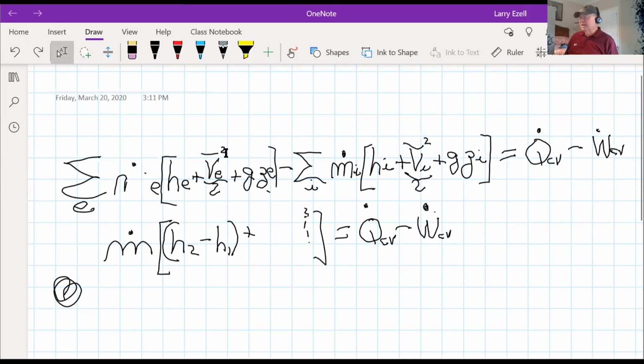But the important thing in the second law I was going to mention: this energy equation, or the first law equation, doesn't say anything about how much. It says that energy has to be either here, here, here, or here. It can't disappear and you can't create it. It has to be accounted for in this equation. But what the first law doesn't tell you is how much of this fluid energy is converted into work or into heat. Are there any limits? No, you could have all of the fluid energy converted into heat or into work.